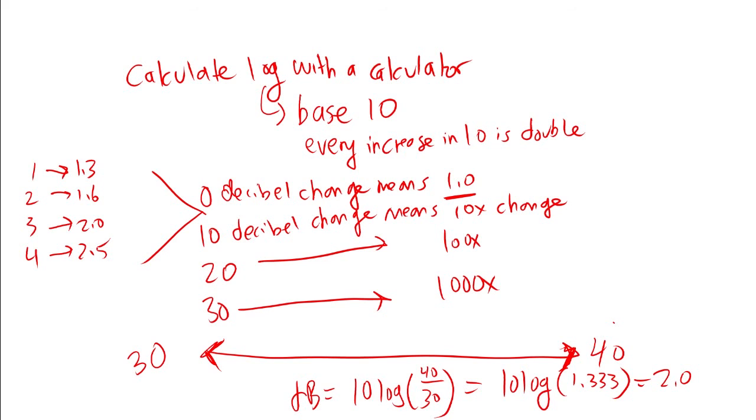And that's fine. We just gotta know how to increase the power. With increased power comes increased noise though. So if we're losing a ton of power, we can't just crank up the power forever because we'll get a lot of noise that we have to filter. And we'll also have to make sure the transmission medium can support it. And we have other things to think about.